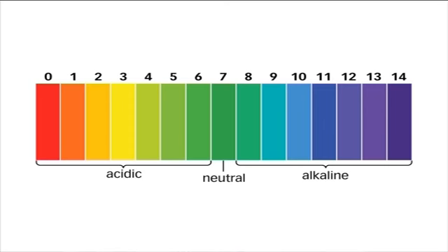To represent the steps thermodynamically relating to the state of refrigerant, the p-h chart is used. The p-h chart gives directly the changes in enthalpy and pressure during evaporation, compression, condensation, and expansion processes for thermodynamic analysis, which is important to consider while designing a refrigeration system.